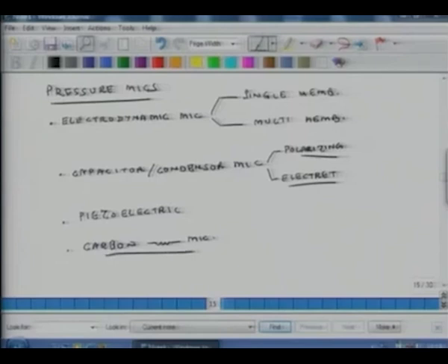but earlier, especially in a lot of analog telephones, you would have these mics, and the way they operate is there's a small button in the device which is packed with carbon granules. As the pressure wave hits a surface of this button, it presses. So the resistance of the carbon granule changes accordingly in some predefined way. That resistance change is sensed by the electronics, and that gets recorded or converted into sound. So it was used a lot in old type of telephones, especially those black telephones. You may still see some of them lying around, and also in recording industry they were used.